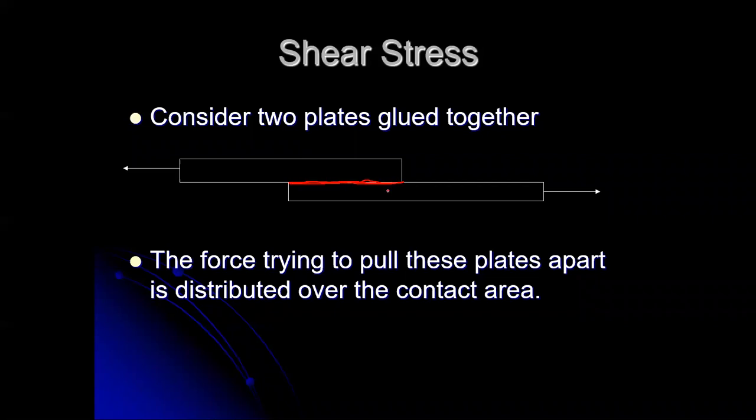That's a clue as to what was fighting the shear stresses that were in the system. The area that becomes exposed when it breaks. That can be a useful way of figuring out what area is the important area in figuring out shear stress.